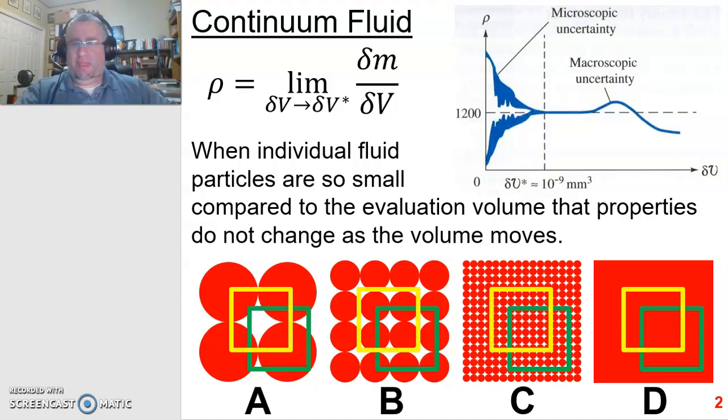The best way to describe this is to give you an example, which is the fluid mechanical property of density. A standard definition of density is just a mass over a volume. So I can also say that it's just a differential mass over a differential volume. What that does is allow me to change the size scale of interest that I'm looking at. And I'm going to use this to show you where density stops making sense, and therefore a size scale at which the continuum fluid assumption also breaks down.